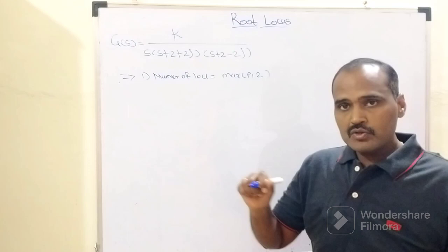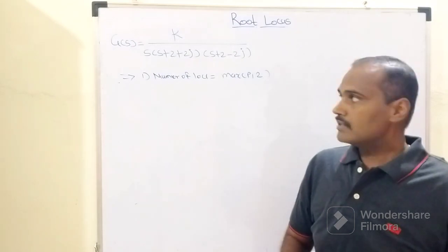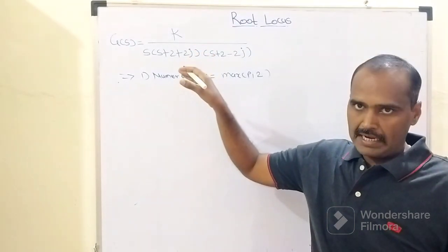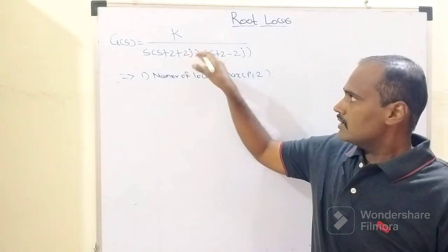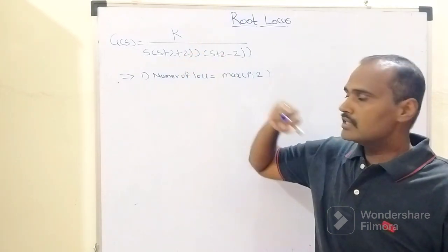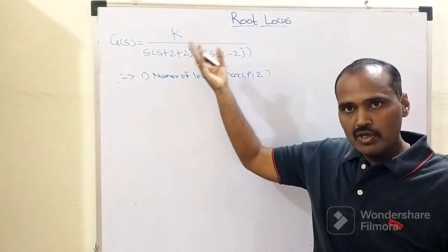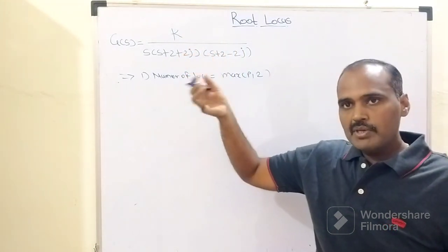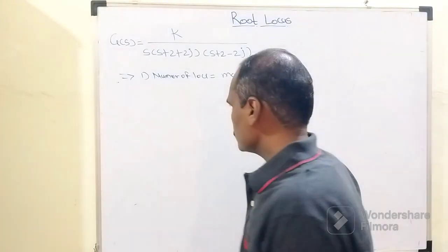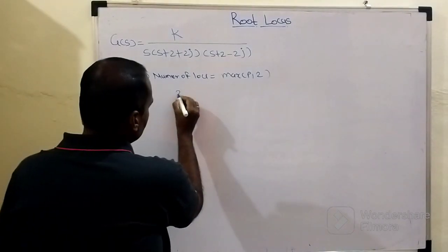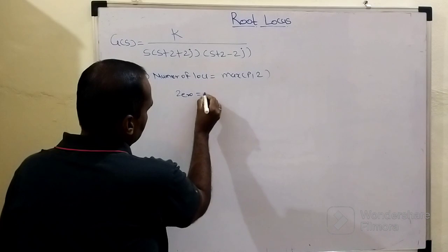So as a result of doing this, first of all we need to determine how many poles and zeros we have with us. Carefully, if we observe the numerator polynomial, within that numerator polynomial we don't have any term belonging to s, so we come to this conclusion: number of zeros equals 0, meaning we don't have any zero here, right?